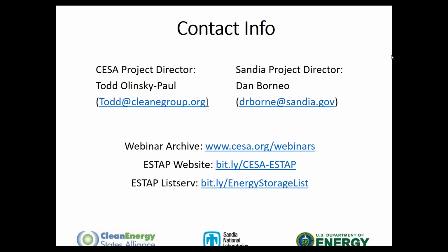Okay, first question for the panelists. How are modeling teams currently solving the lack of reliable 15-minute and sub-15-minute interval data for end users? And this is primarily for behind-the-meter systems, when designing energy storage systems in developing markets where this data oftentimes is simply not available or does not exist. Yeah, so maybe I can take that. That is a challenge. So this is for behind the meter, so for example, you need load data.